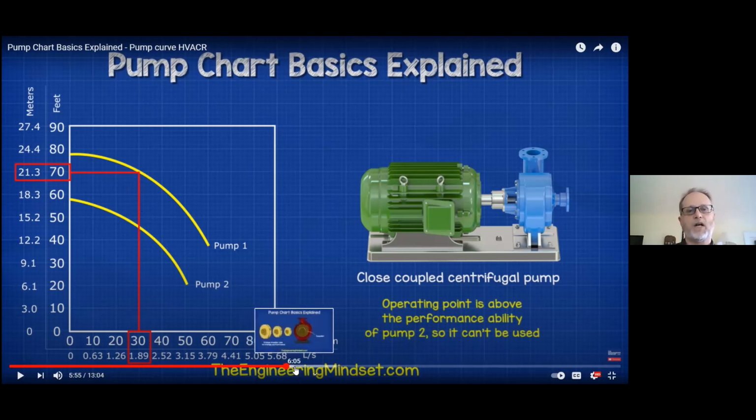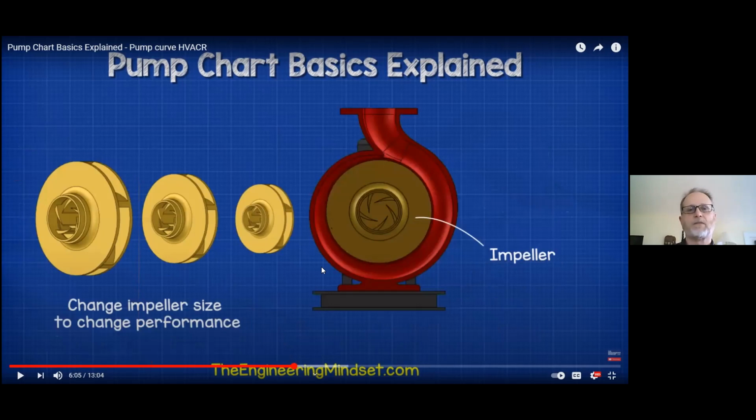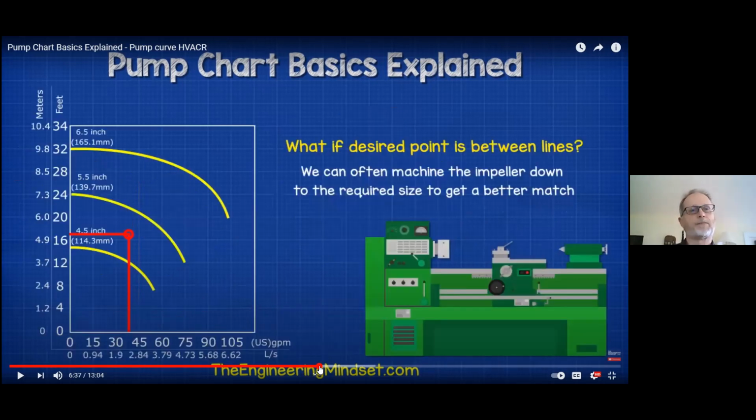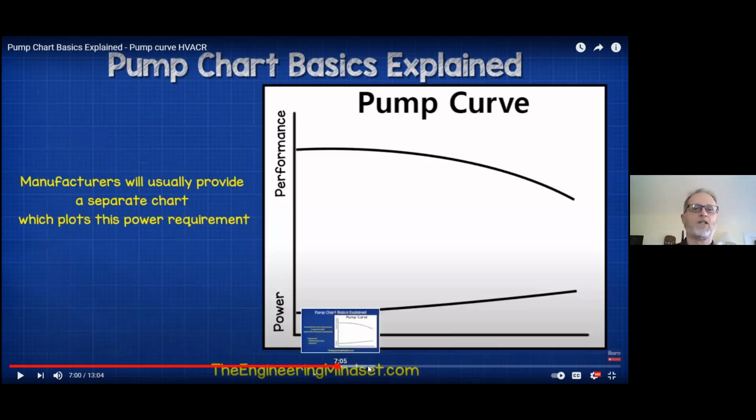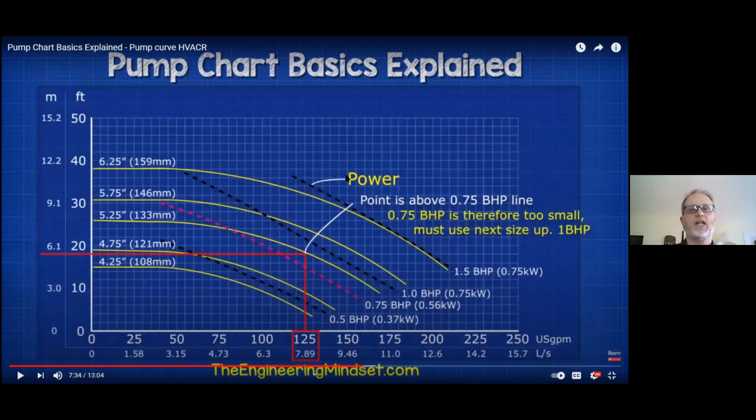Now, this video goes on to talk about other things, like the size of the impeller that can change, within the same volute, how much water and how much efficiency we have. I'm not going to worry about that. You won't have to. But the other part of that is we can now create and overlay horsepower. We can specify the power and the efficiency of the pump and the motor so that we can actually choose how many horsepower based on the size of the impeller.